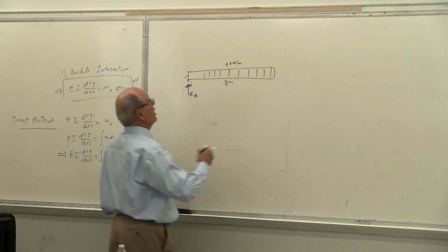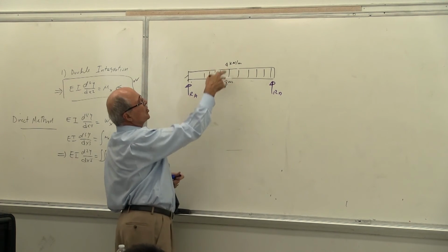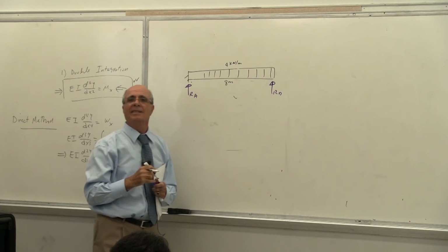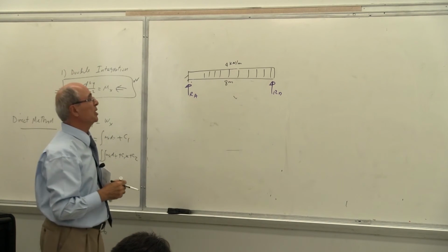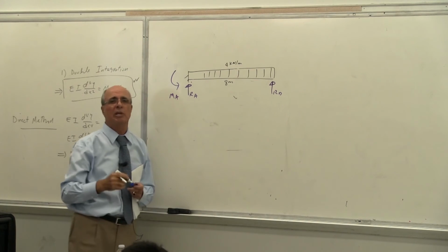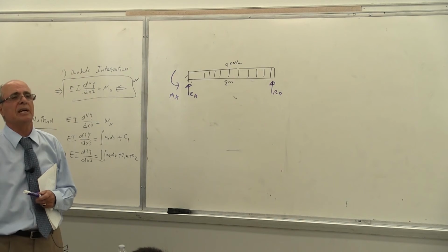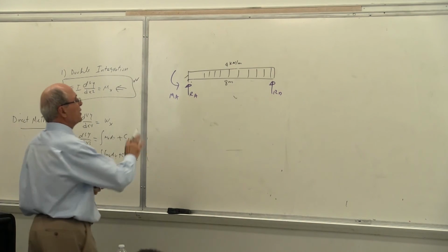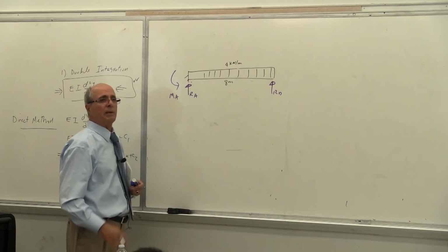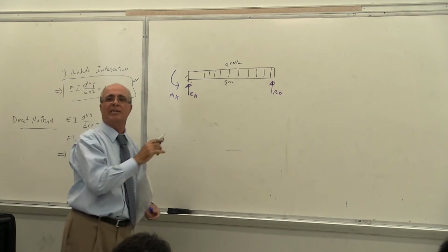If you put here RA and RB, so obviously this is 32, this must be 16 and 16. That's another mistake. Some people put MA here, but they forget to put it in their equation. I have seen all sorts of it, but this is the same, as if you forgot about it. Is that correct or not? Short story, this is not solvable by statics. We have to go through this system to solve this one.